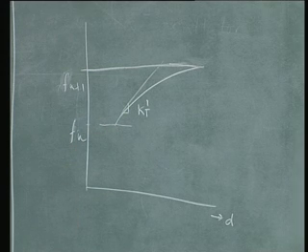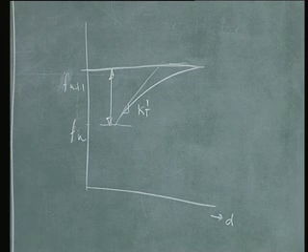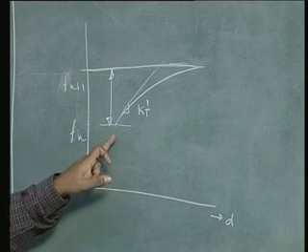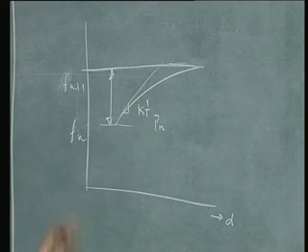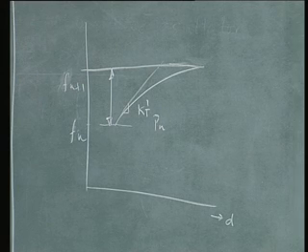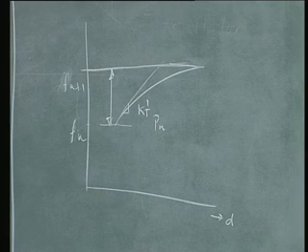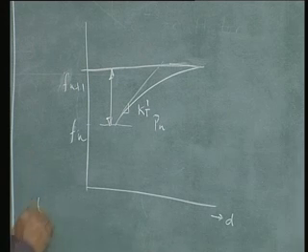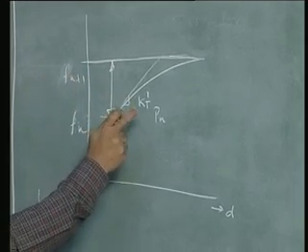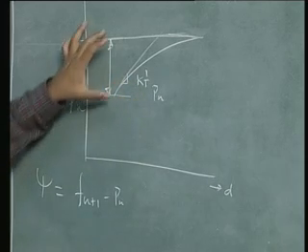Now, when I start this iteration, what is the error? That is my error, because my internal forces have now equilibrated up to Fn. My internal forces, if you remember, we had called this Pn. Now, at the point of time when I start my journey towards n plus 1, what I know is sigma n, and that sigma n gives rise to Pn. So, if I now calculate the internal forces at that point of time, what I will get is Pn. And my error, if you remember, was the difference between the load that is applied and what you have got internally. So, Fn plus 1 minus Pn. That is the error.